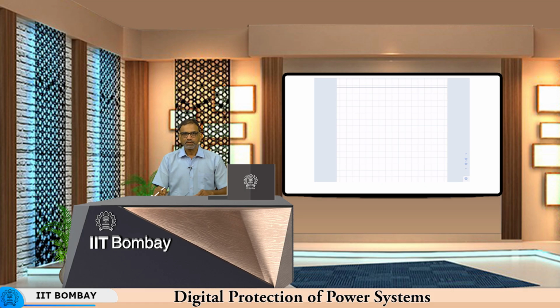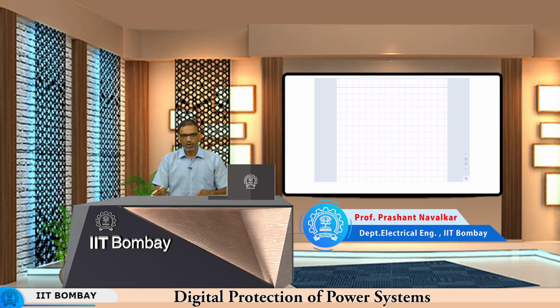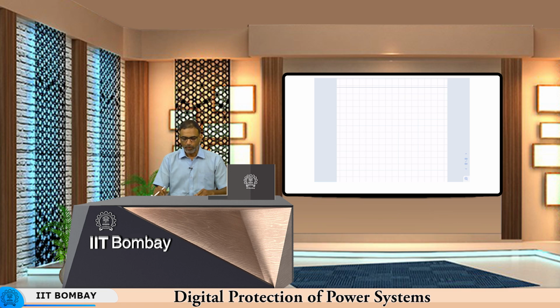In the last lecture, we saw overcurrent relaying and earth fault overcurrent relaying. Today, we move on to a new type of relaying, namely distance relaying. Now, in distance relaying, unlike in overcurrent relaying, we use two inputs. That is, we use the input from the current transformer as well as the voltage transformer or the potential transformer.